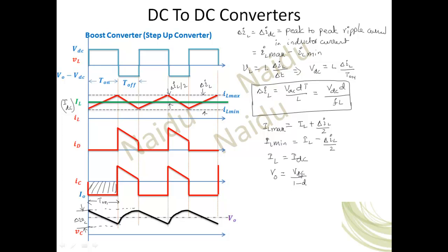Okay, remember that. Now if you go for the power balance equation, whatever the source is supplying, the power is consumed by only the load. Then in that case what will happen? VDC into IDC equals V average into I average. So from this you can take it as V average divided by VDC equals IDC by I average, that is equal to, you can see that remaining is nothing but 1 by 1 minus D. Okay, this is the power balance equation.